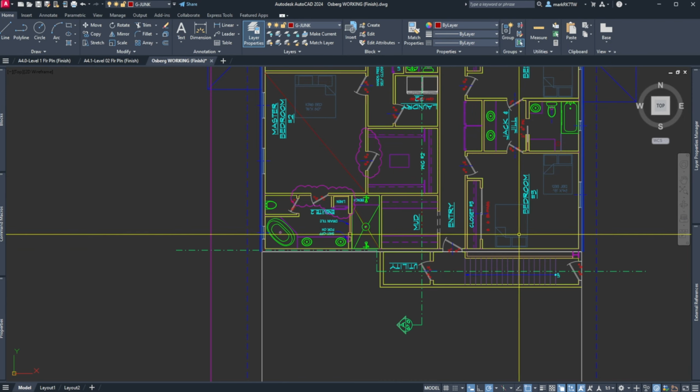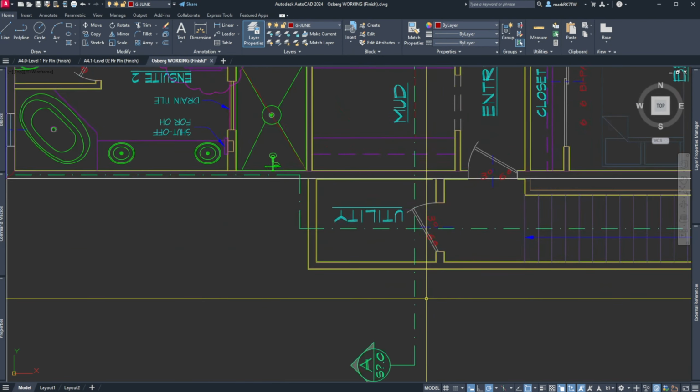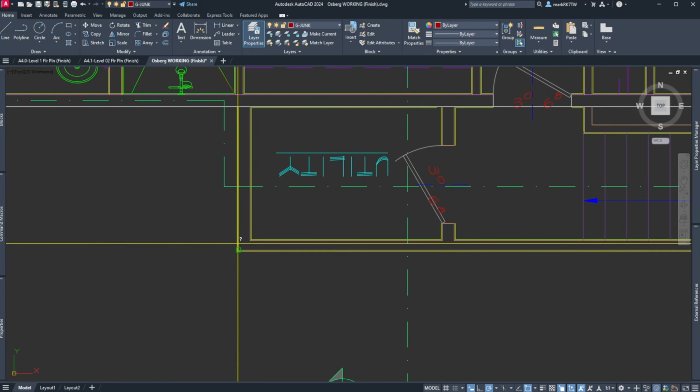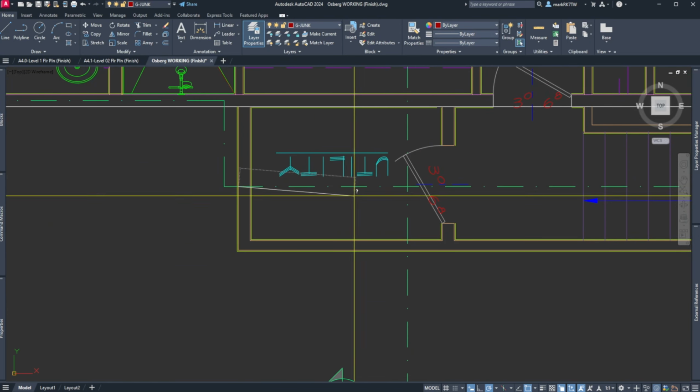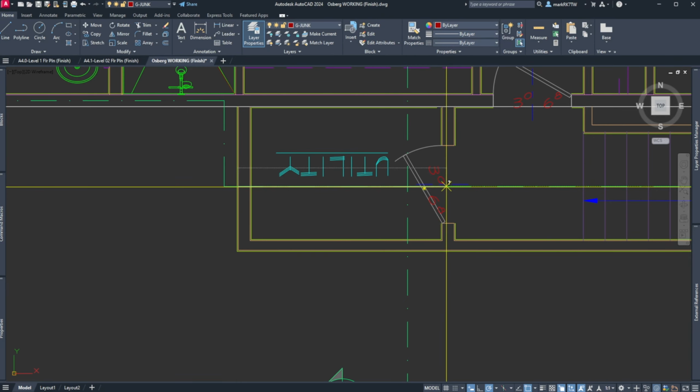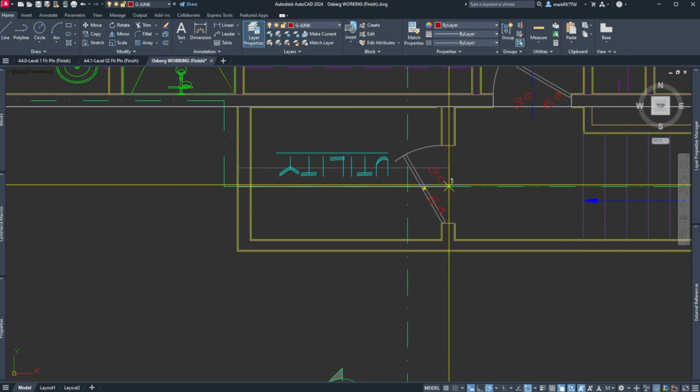They will probably run in this direction, and so what I probably will do, let's see if we have a 2/3 backspan. 2/3 backspan is just a great rule of thumb. And so if I'm here, I'm at 710, so let's call it 8. In fact, we can come all the way out to here. So I'm at 8.2. So I need to have 4.1. 8 and 4 is 12. And so I'm at 5.1. So I don't really have a full 2/3 backspan.